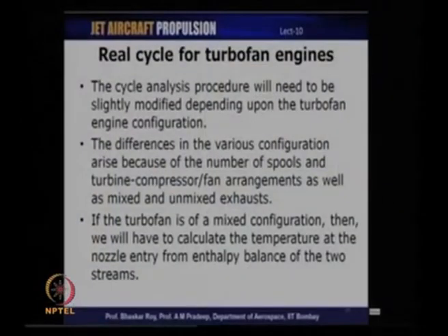So, in this ideal turbofan, the real turbofan cycle analysis, what we have discussed is for a turbofan with two separate nozzles. The cycle analysis procedure will be slightly different depending upon the turbofan configuration, and those differences will need to be taken into account while carrying out cycle analysis for these different types of turbofan. If it is a mixed configuration, then we will need to calculate the temperature at the nozzle entry from an enthalpy balance of the two streams.